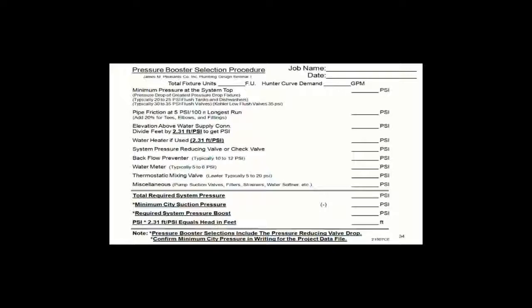And very quickly, I don't want to bore you with this, but as an old guy who's been in this business way too long, I see things. And here's this 100-room apartment example that we just talked about. And in red, I just popped in all the numbers we talked about, 800 fixture units from 100 rooms, 180 GPM demand, came through all those pressures we talked about. And now you got a permanent record of what you did and why, and then you know the numbers. And my pressure booster needs to be what? 180 GPM with a boost of 56 pounds.